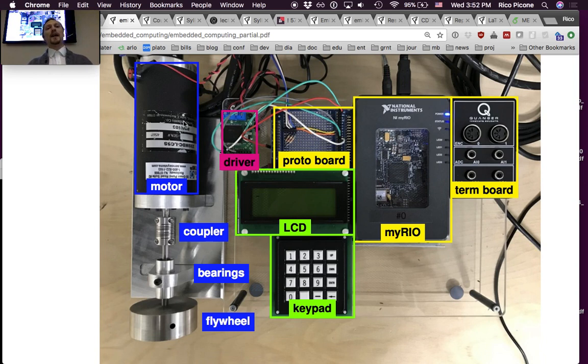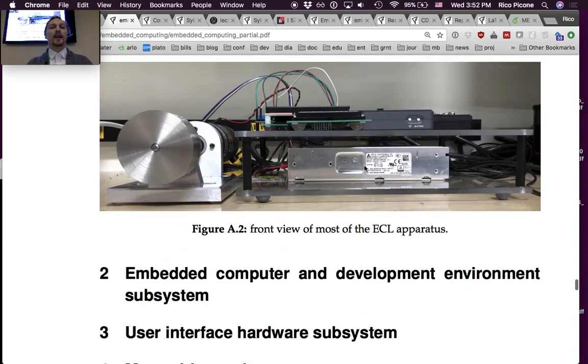So what we do is we have that separate DC power supply. This thing can supply some power, okay? But it's not a variable power supply. And actually that's one of the main differences between this system and the system that they have at UW. They have what's called a linear amplifier. So they can just give it an analog voltage at a small power, and it'll put out a high power voltage at the same signal, at the same level. We don't want to go that route for a few reasons, mainly cost. The cost difference is significant.